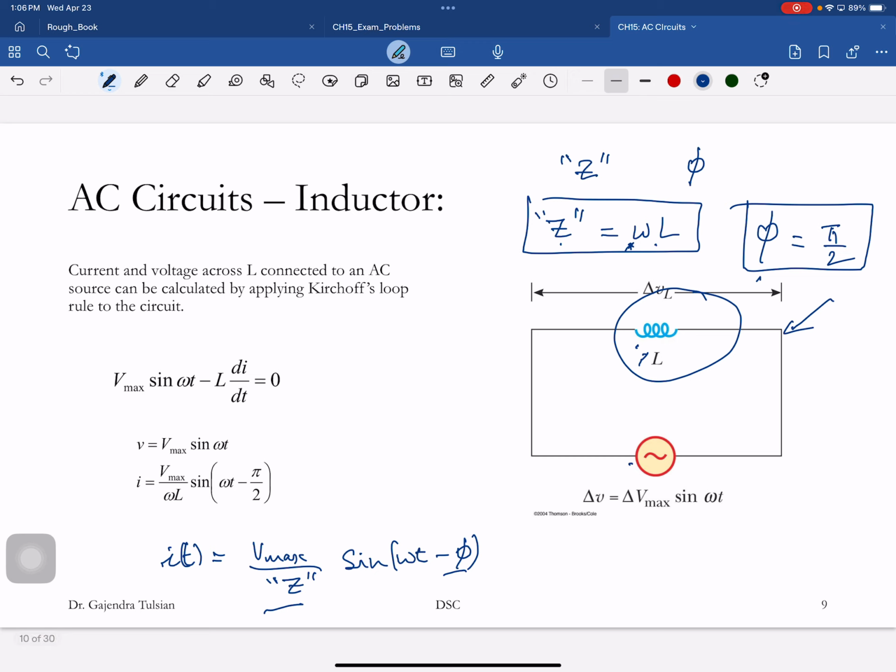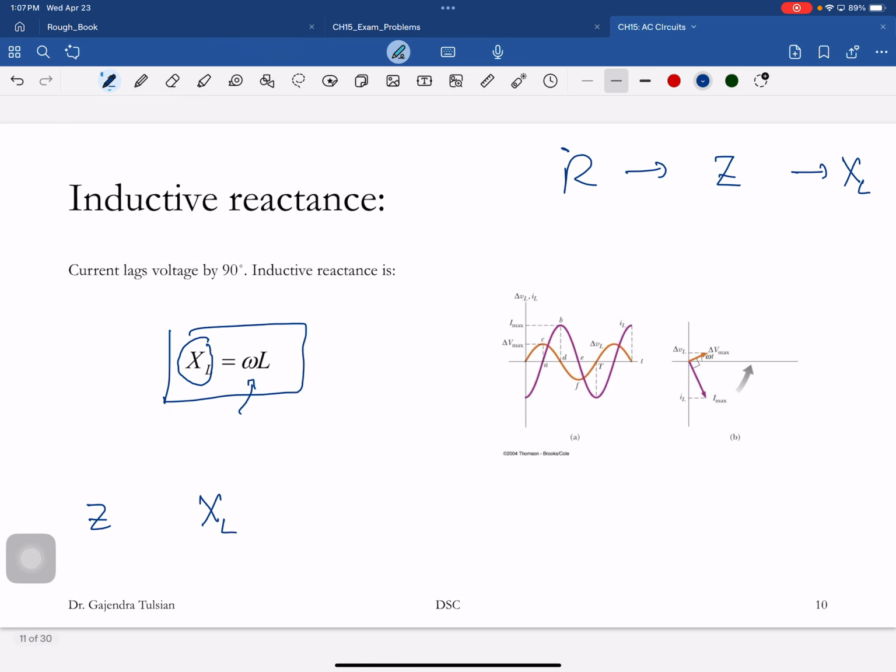We'll do the phasor diagram. Here is the voltage phasor, and you see the current is 90 degrees behind. So here is the voltage phasor, and here is the current, 90 degrees behind, and then you rotate this. If you want the instantaneous value, just take the y component of those vectors. All right, so we've done R, we've done L, and now we'll do C.